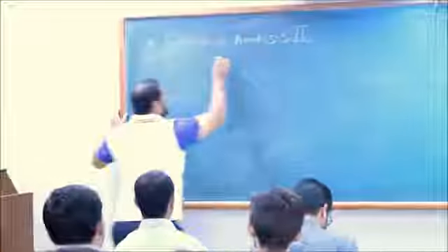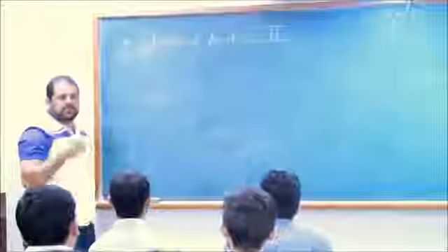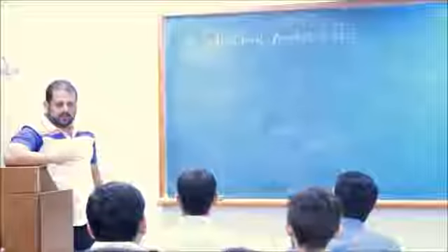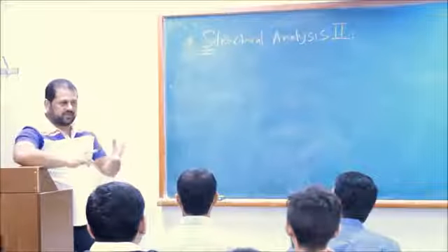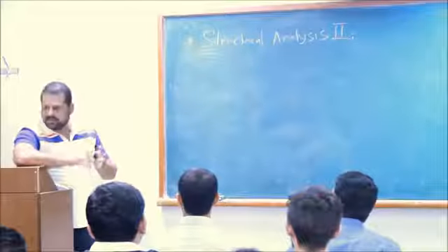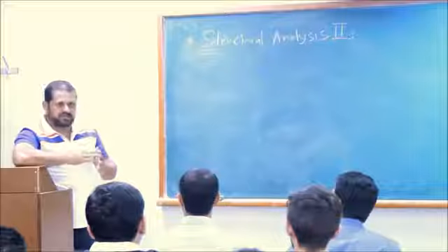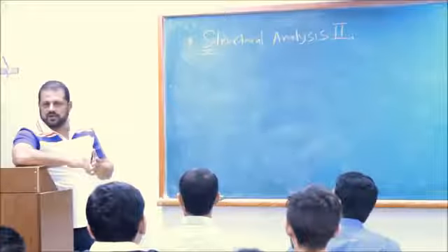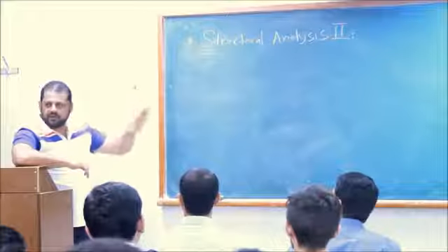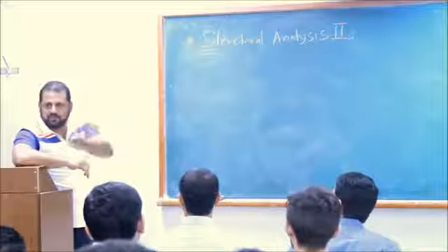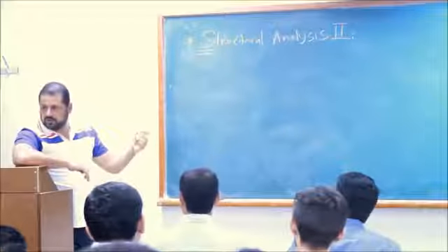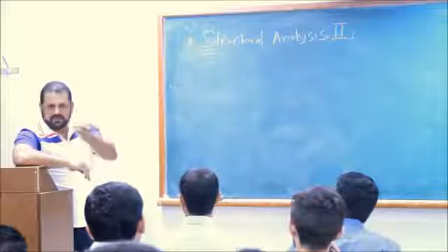Studying is indeterminate structures. And you took a course called Structural Analysis 1. You solved determinate structures. Okay, you did with every kind of determinate structures: beams, frames, trusses. There is also complex truss, we covered complex truss, space truss. When we say determinate structure, the available equilibrium equations are enough to solve the problem or to find the unknown reactions.